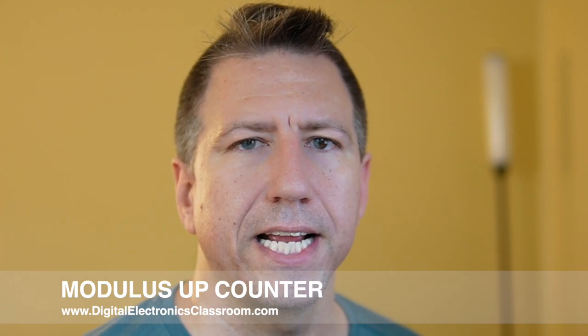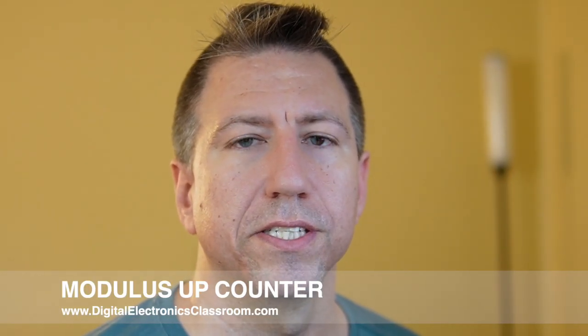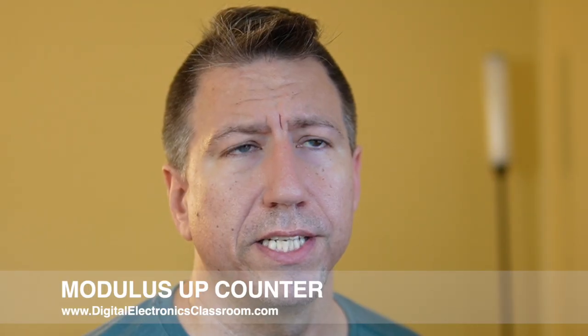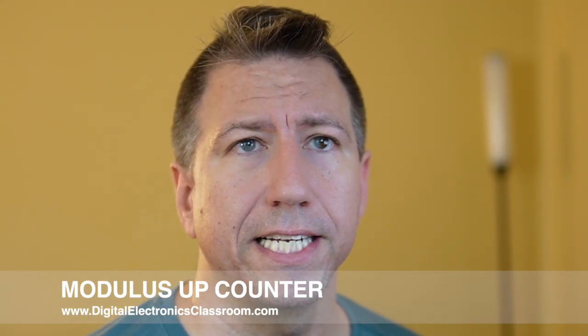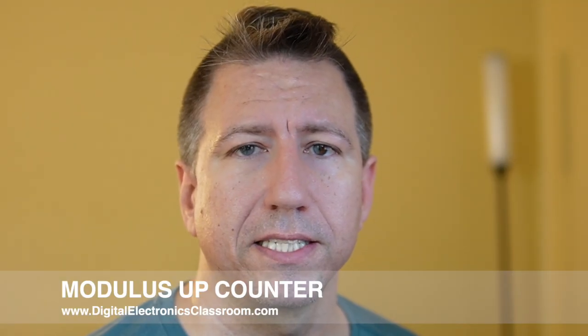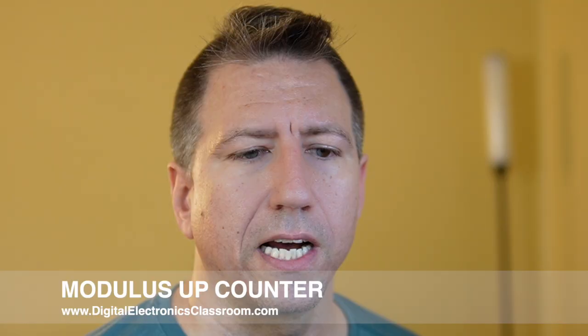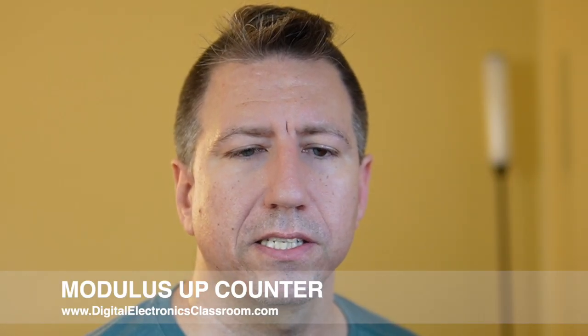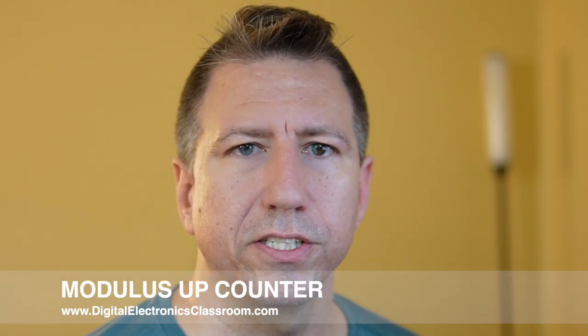And so today, in our example, we're going to count from the number 3 to the number 9. So what modulus would that be? 3, 4, 5, 6, 7, 8, 9. So that's going to be a mod 7 counter. Okay, so we're going to look at how we set this up, how we make it start at the number we want it to, and how we make it end at the number that we want it to in this video. So let's get started.